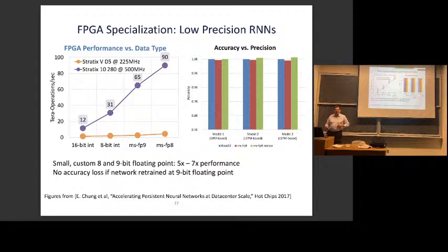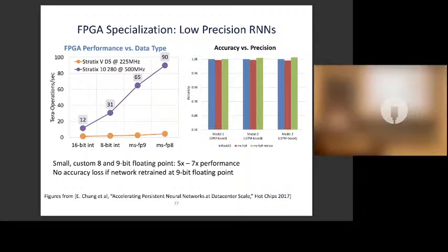So not only is this a small floating point where it's only got 8 bits, the mantissas are really small. They usually wind up with 2 or 3 bits for the mantissa, and the rest are the exponent. It's kind of like the opposite of most normal floating point encodings. But by making that kind of custom encoding, they get good accuracy, and the hardware units become very small, so they get very good compute throughput too.